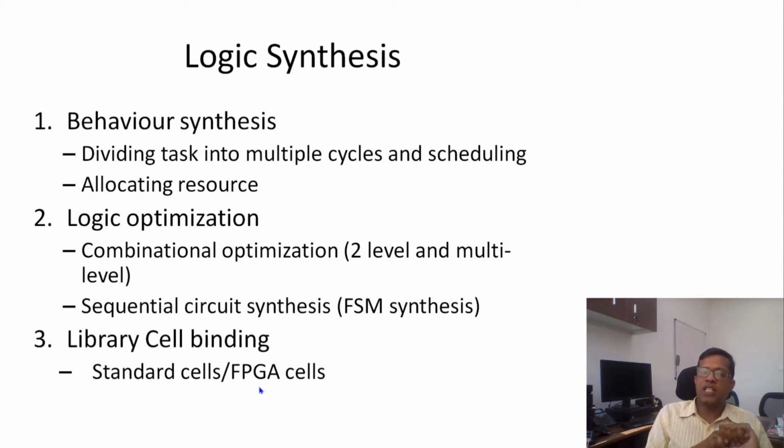And then the second step is logic optimization, logic synthesis. Here, from the behavior, we get to know what logic is there. That logic has to be optimized using two level and multiple level synthesis, multiple level optimization. Here I would again categorically say that although during the course we have focused more on two level synthesis, eventually multiple level synthesis would be